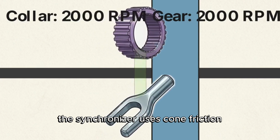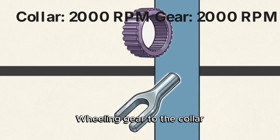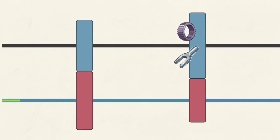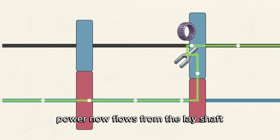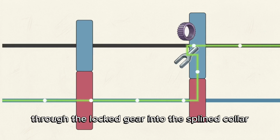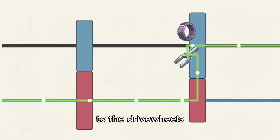The synchronizer uses cone friction to match the rotational speed of the freewheeling gear to the collar before the dog teeth engage. Once speeds are matched, the collar locks into the gear. Power now flows from the lay shaft through the locked gear into the splined collar, and finally out through the main shaft to the drive wheels.